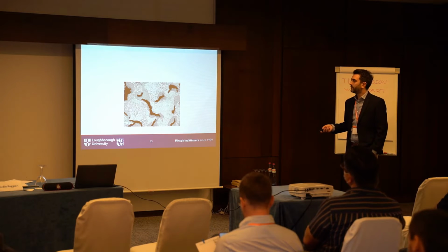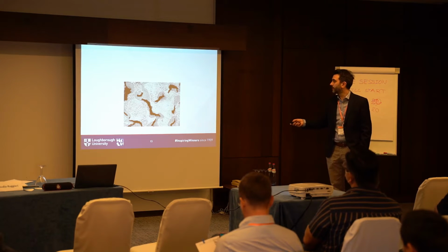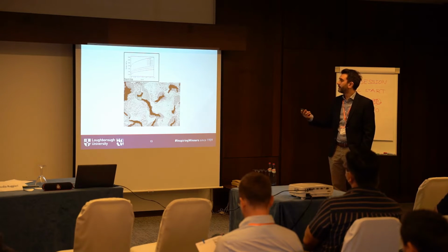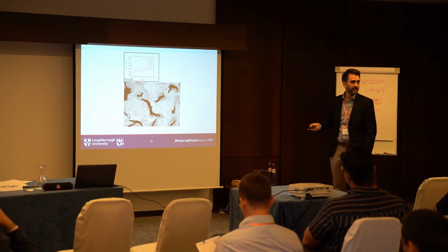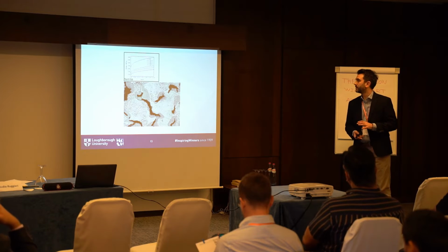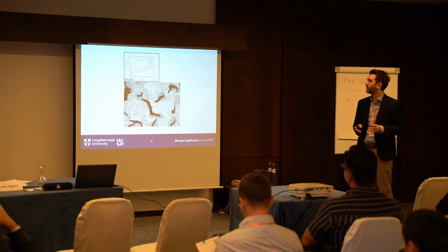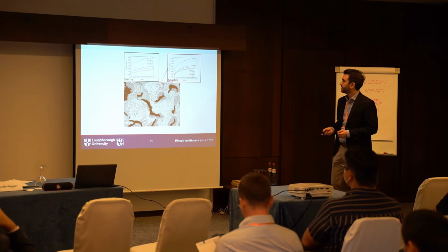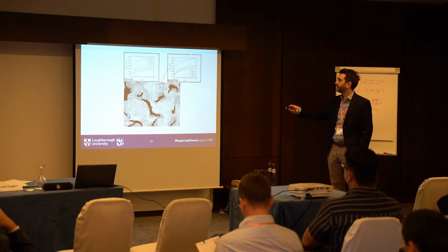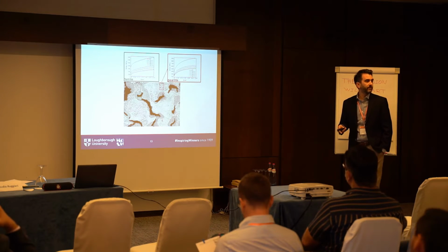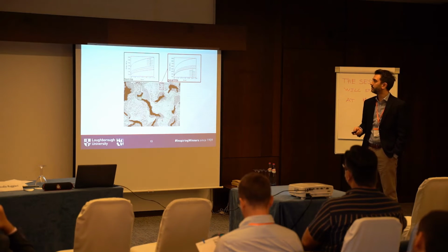Now, when it comes to the constitutive laws, again for the modeling, this is the micrograph I used earlier. This is a piece of ferrite, so we have data for that are temperature dependent, from room temperature up to 500 degrees. This is the operational range of this material. The automotive industry tries really to push this envelope higher, 550, 600, etc. Same for the perlite, temperature dependent data. This you can use as is in a model, or you can use your favorite Johnson Cook or another model.